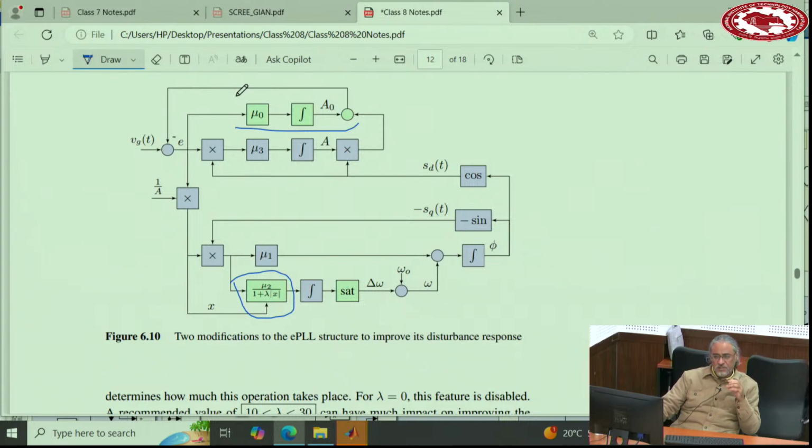The reason was there was this DC added as a result of this procedure to the waveform, and when a DC is added, PLLs generally are sensitive to DCs. So if you have some DC, even 10%, 8%, 5%, the results will start causing a lot of errors. So you need to remove it. Okay, so this removes the DC.